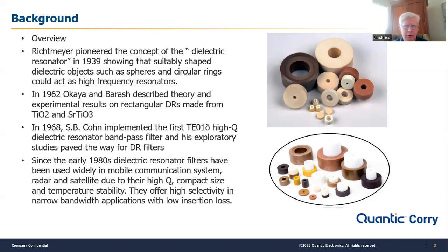Today, there are a lot of different uses for dielectric resonator filters. They have really high Q, which means anytime you have high Q components when you're building your filters, you have low losses. So you can get really low insertion losses with dielectric resonator filters, or really narrow bandwidths with decent insertion loss. So there's a lot of advantages to using them.